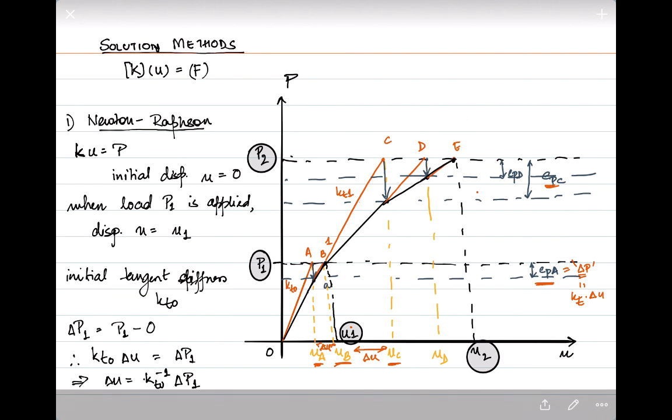This in general describes to you the Newton-Raphson method. So we need a lot of equilibrium iterations to be able to get to a solution within a certain load increment. So clearly, if we apply a sequence of increasing load levels and we iterate to convergence for each of these load levels, so we kept iterating till we got to the point, then by convergence we mean reducing the error, so that we are every time at a stage of equilibrium, we are able to construct an adequate P versus U curve or F versus U curve in a problem.